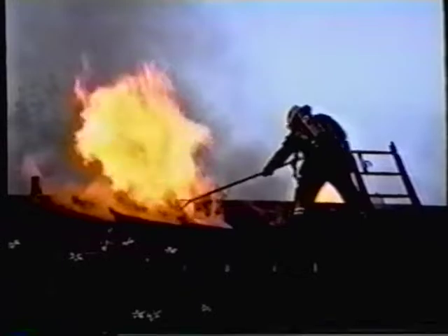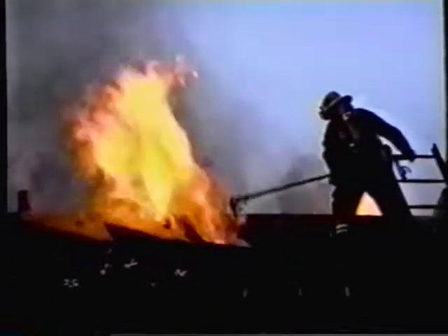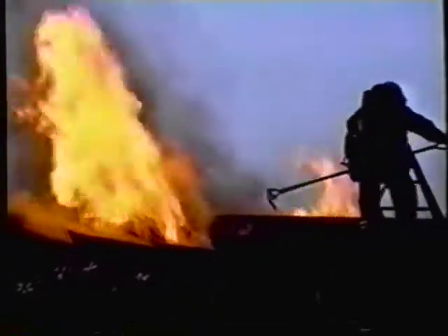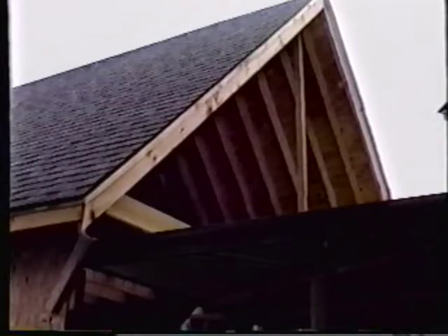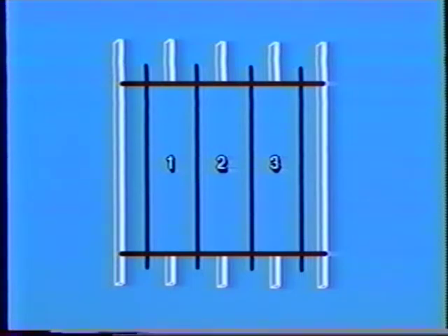When the 4 cuts are finished and you are prepared to open the hole, bang down one side of the plywood box so that it rotates on its rafter axis, tilted in the fashion of louvers. The hinged cut is particularly effective for plywood decking because the nails used to install the material and the size of the plywood sheets make it difficult to pull cut roof sections. Should you require 2 horizontal cuts and 4 vertical cuts between the rafters, create 3 louvered sections, more than sufficient for this operation.